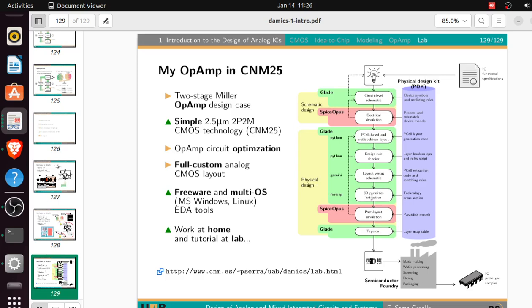Then parasitic extraction. By now, from your device physics, you know you're fabricating a MOSFET, right? But we usually have some capacitance effects, some parasitic capacitance. Some are intrinsic, some are extrinsic, like what you never intended. They are parasitic because they were not intended. That's not what you want to design.